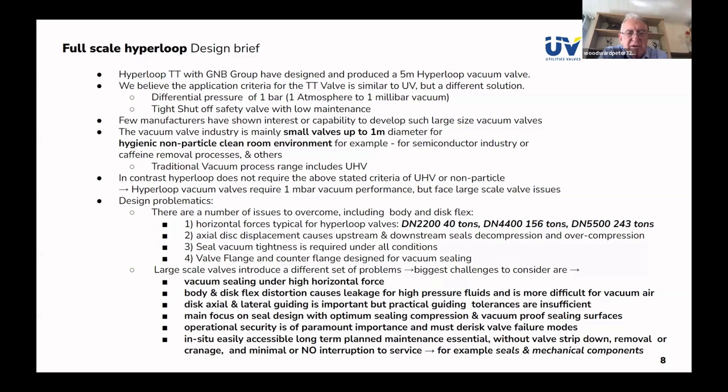We have always aimed for 100% seat tightness for fluid valves under the highest pressures going up to 40 bars. But it is a question of avoiding the distortion and flex, which of course would upset the sealing. And with vacuum, it's more sensitive.